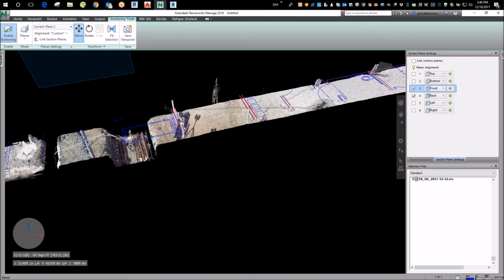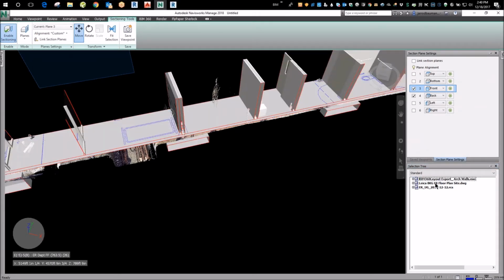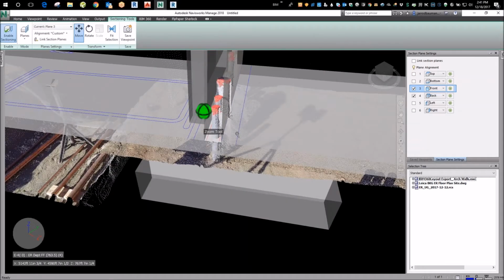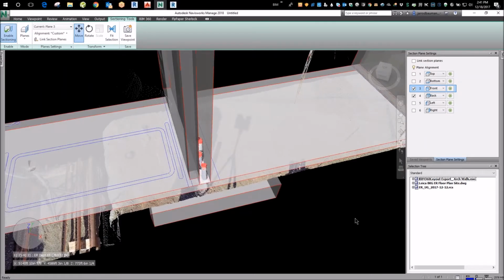All right, I'm going to do you one better though. It gets better than this. Okay, so the CAD background's nice. Let's turn our 3D back on, our 3D CAD wall or our 3D Revit model. Unhide that guy. And let's just make the whole thing somewhat transparent, like a 30% transparency. Okay, so did you guys get it to where you've got both the CAD, the scan, and the AutoCAD or Revit 3D in there?